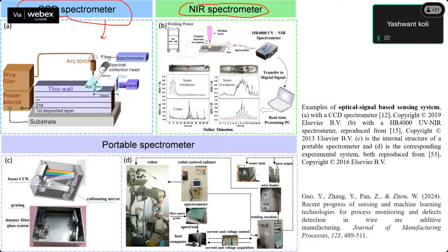So what are the strengths, basically why are we using optical sensors? Because we get non-contact, real-time monitoring data, high sensitivity during welding, effective for porosity. We need good real-time data for porosity, oxidation, penetration, spatter, and contaminants. So these things can be analyzed, and we can optimize the process parameters. These data are very helpful. It is also less affected by the environment compared to X-ray or ultrasonic testing.